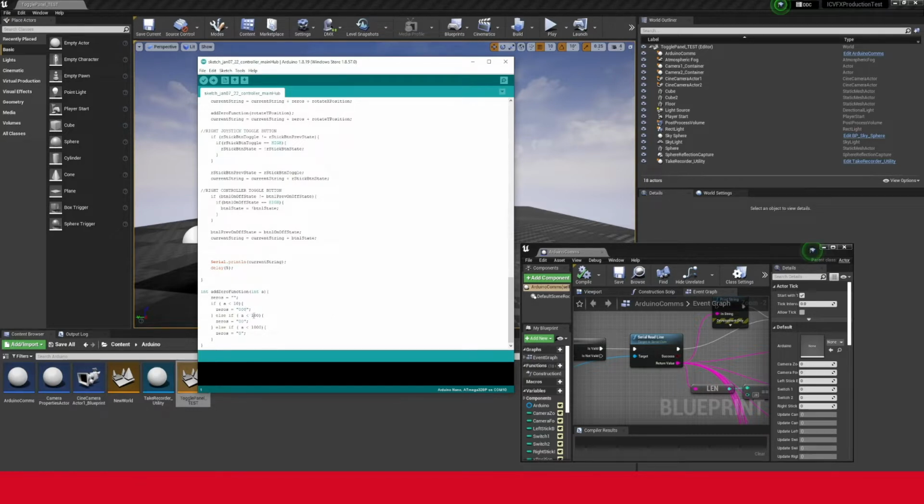If it's a value of 10 to 99 or something like that, it'll add 2 zeros on the front, so 0010, 0099. And the same, obviously, if it's a value in the hundreds, we put a 0 on the front. Anything higher takes up all four characters as well. By doing that, we ensure that we always have 4 characters for each potentiometer and joystick.